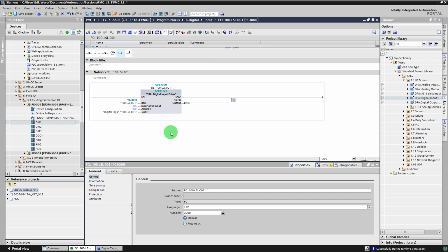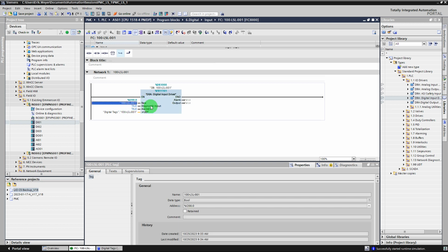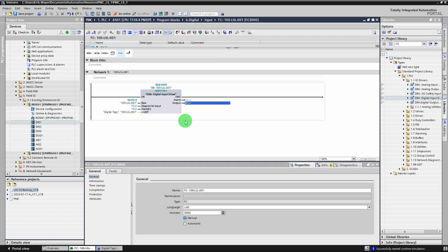Then I've got two outputs. My alarm output, this is subject to the alarm enable. If this is not enabled, then regardless of the input, I would always have a true signal coming from this. Then the general output. This output is derived from the input through the input filter and output filter, and this will typically be used inside your program to either be an interlock or, let's say, a prerequisite on a sequence, up to your discretion.